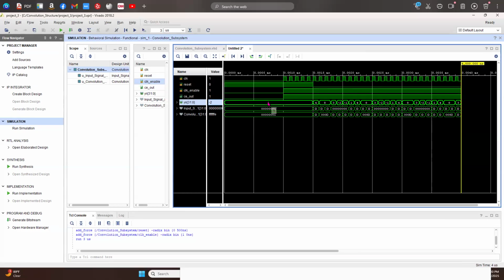Now you'll see the correct expected output data flowing, 1 sample per clock cycle, just as expected from our Simulink model. This confirms that our HDL design behaves correctly in simulation, a critical step before loading it onto real hardware. In the next video, we'll move forward with synthesis and implementation on the FPGA.